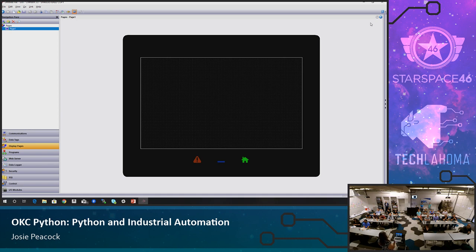But that's the beautiful thing here, Crimson 3.0 now includes an OPC UA server in their HMIs. So if somebody designed a machine that says, hey, I put this HMI on here, I have the OPC UA, here's all of the data that I need to put into a database and save and manage, then suddenly you just point to this IP address, use the OPC UA library and go for it. And I know I'm changing library classes, so you have to excuse me.